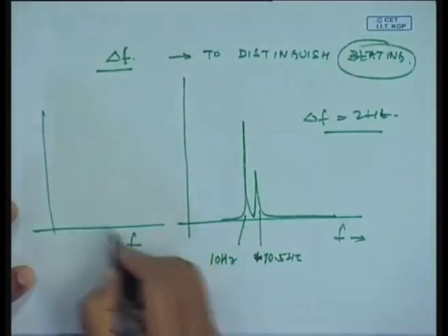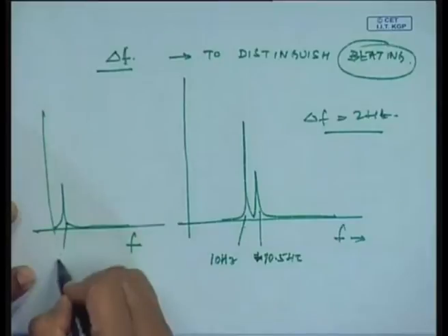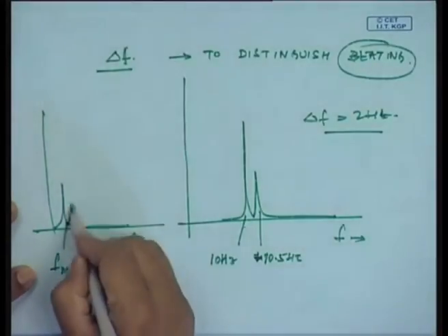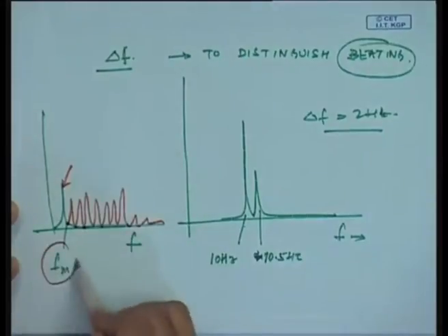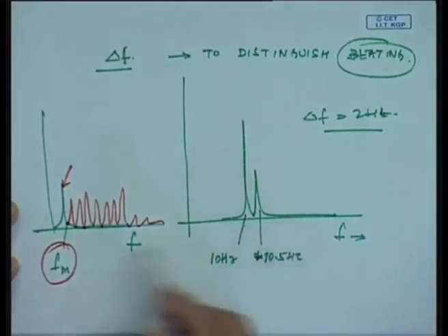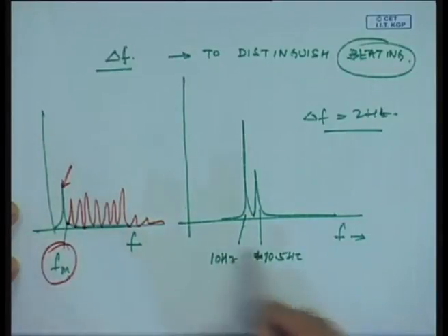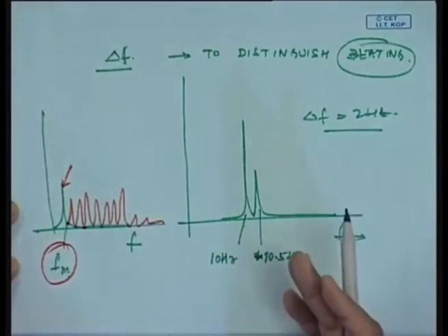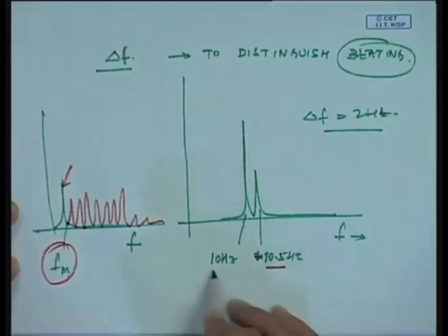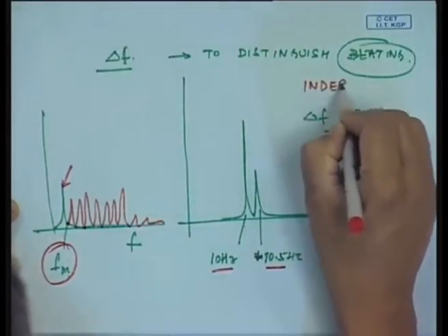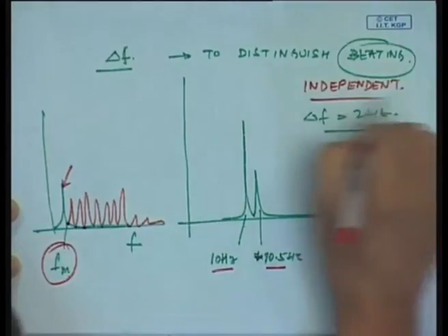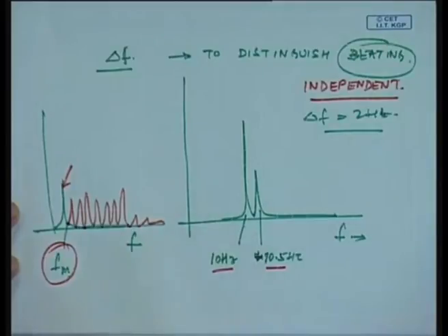So, amplitude modulation, because if I have an FFT of a signal wherein there is a modulating frequency fm of a very low frequency, this will be, as I was telling you, very easily obscured in other noises. So, envelope analysis is an excellent method to find out fm, okay. But there may not be any other frequencies next to fm. If I have finer resolutions, I can check that, but if I see two frequencies, 10.5 and 10, which are not related to each other, then I can say the signals are independent and they are responsible for beating of the signal.